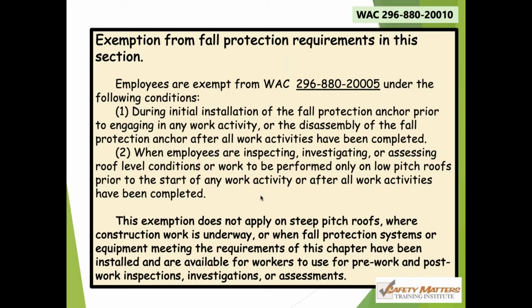If you guys are measuring the roof to determine how much materials you need, if you're inspecting it for damage without removing anything, if you're assessing the rooftop to determine what type of protection you're going to provide, you have an exemption from fall protection requirements. Okay, this is exactly where I wanted to end up today.